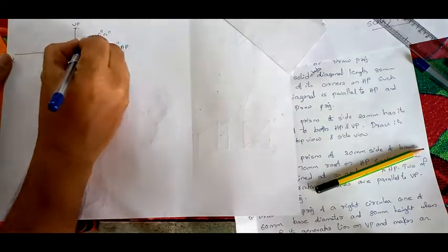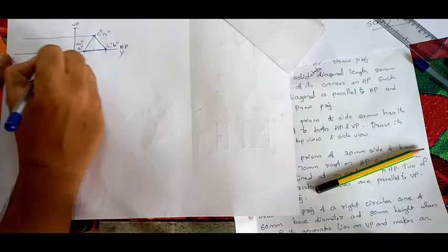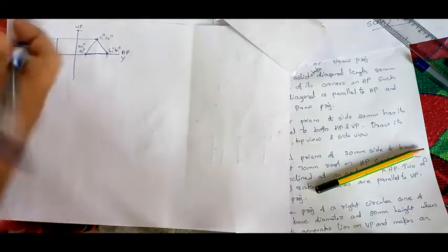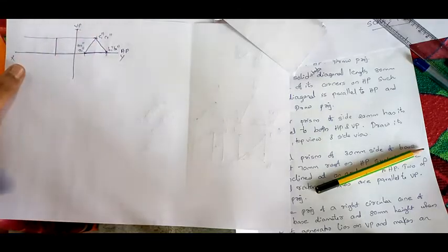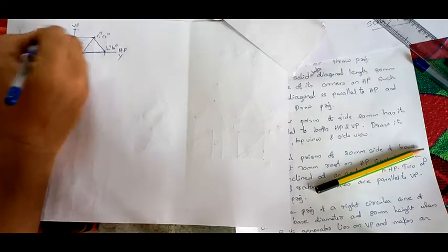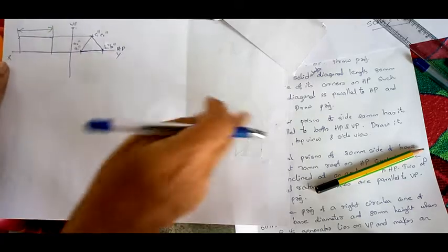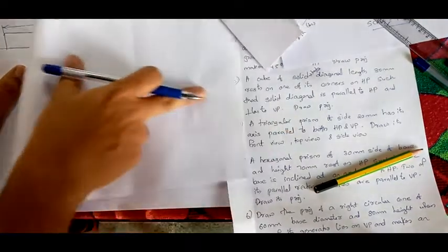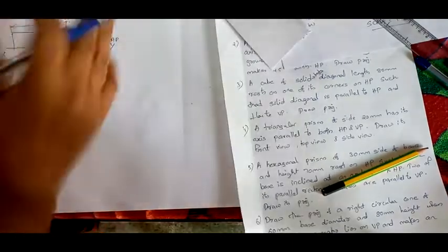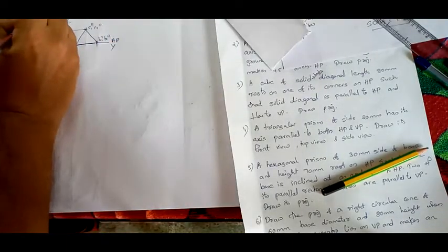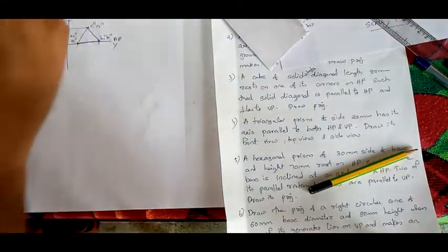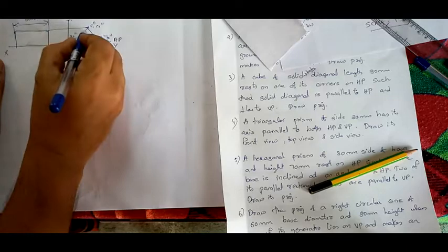Now from here you can correspond, this will be the front view. Take any point here. First draw a line anywhere. Now this will be your height. Height is not given in the question, so you have to assume it, assume 60 mm. So complete it.